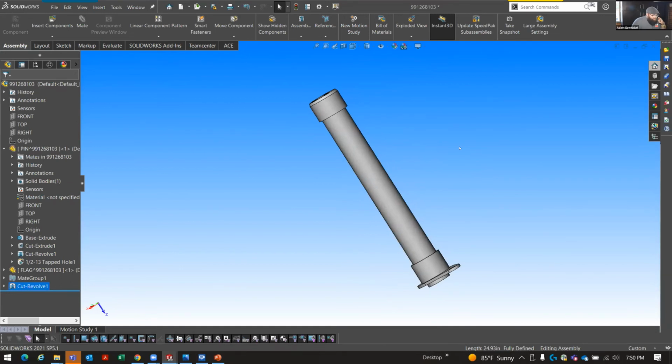So I would want to have just these two ends GD&T to where it needs to be, and then that on the part. These would be the only pieces that need to be surface finished. The rest could be 250 or 125. The guy running the lathe can just hog out the material real fast, only do the super critical parts, and then weld it together.